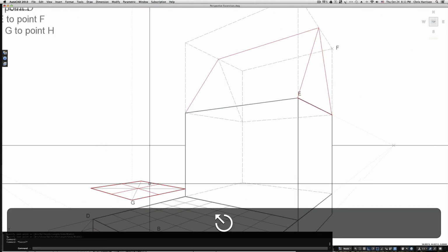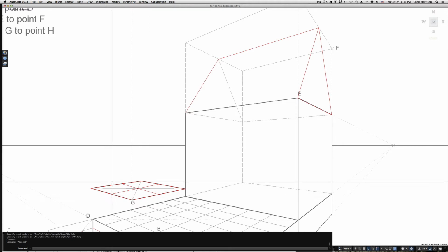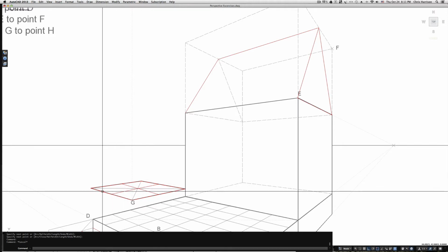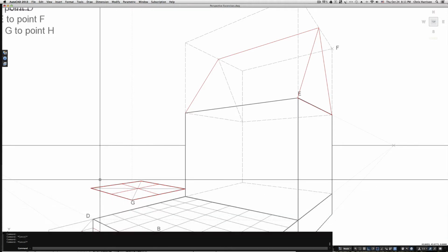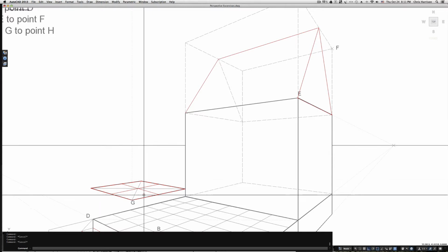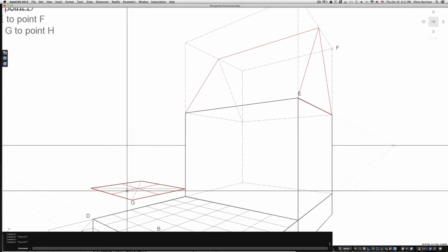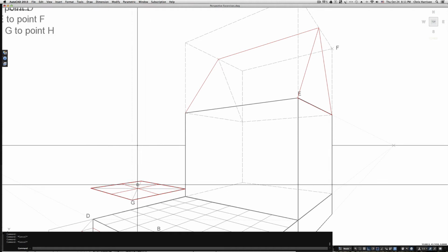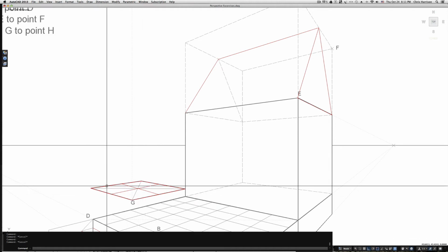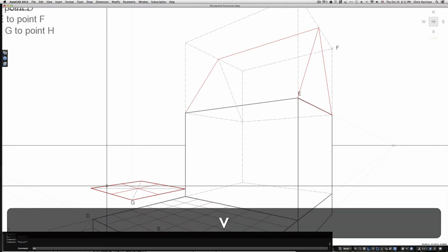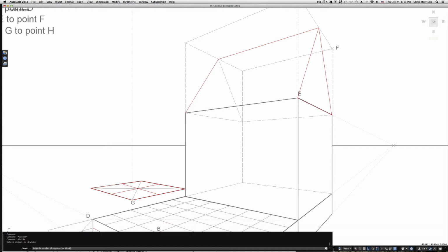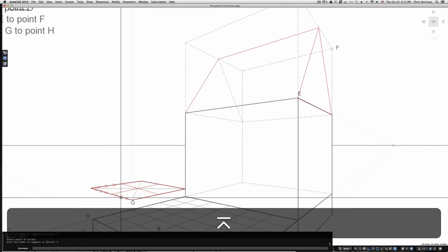Alright. So the circle is going to sweep around here, and you can eyeball this already, but we're going to give ourselves some more marks to help us find the exact point. So I'm going to use my divide tool. I've divided this already, so you see 4 distinct quadrants within the plane, and I'm going to subdivide each of them into fourths. So I'm going to use my divide command again, click on the object and enter 4, and repeat this for each one.